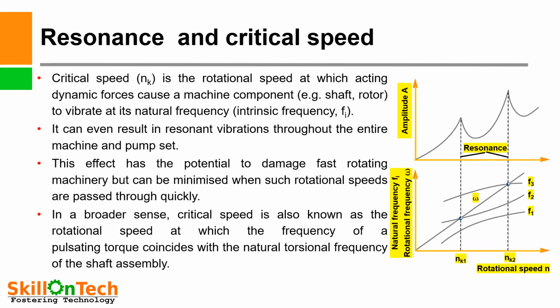Resonance and critical speed. Critical speed Nk is the rotational speed at which acting dynamic forces cause a machine component such as a shaft or rotor to vibrate at its natural frequency, intrinsic frequency Fi. It can even result in resonant vibrations throughout the entire machine and pump set.